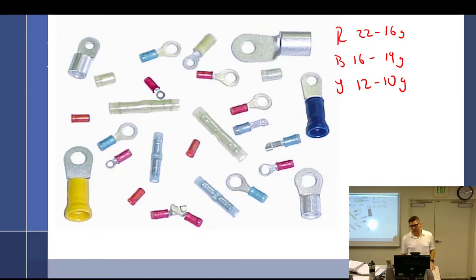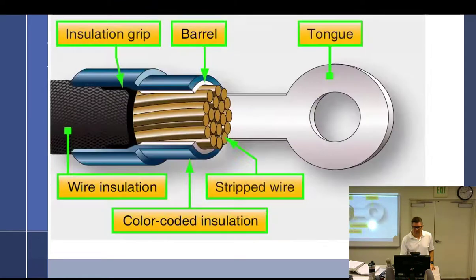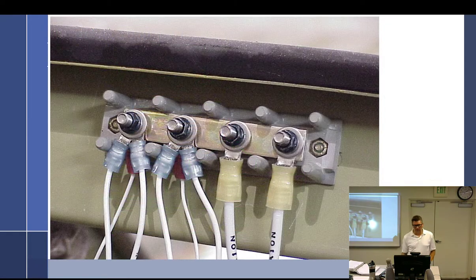These terminal ends, you have a max of 4 per lug. I have a picture of that. Let me see. There we go, 4. It's not supposed to put more than 4 on there. Although I've talked to avionics guys who don't like to split them up, they'll put way more than 4 on a ground, because they say if you put grounds all over the place, you can get this thing called a ground loop. We actually get voltage running around these grounds, which is kind of a weird thing, but no more than 4 per lug is the answer on the FAA test.